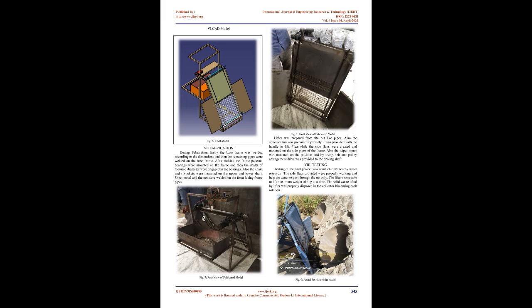Shaft. Shaft is the rotating element used to transmit the power. We will be using a solid shaft. The shaft should have high strength, good machinability, high wear resistance and good heat treatment properties. The materials used for shaft are carbon steels of grade 40C8, 15C8, 50C4, 50C12. MS and EN8 can also be used. We have selected 15C8 for the shaft.